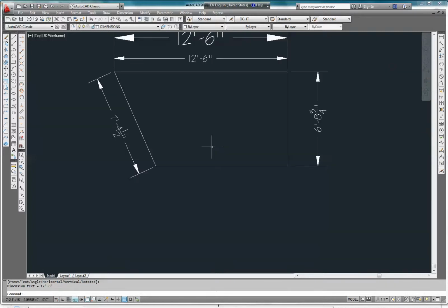And once again, as I said, in the metric system, your overall scale is going to be the same as the scale that you are drawing to. So the equivalent of 1/4 inch to the foot is about 50. It's very close in the metric system.